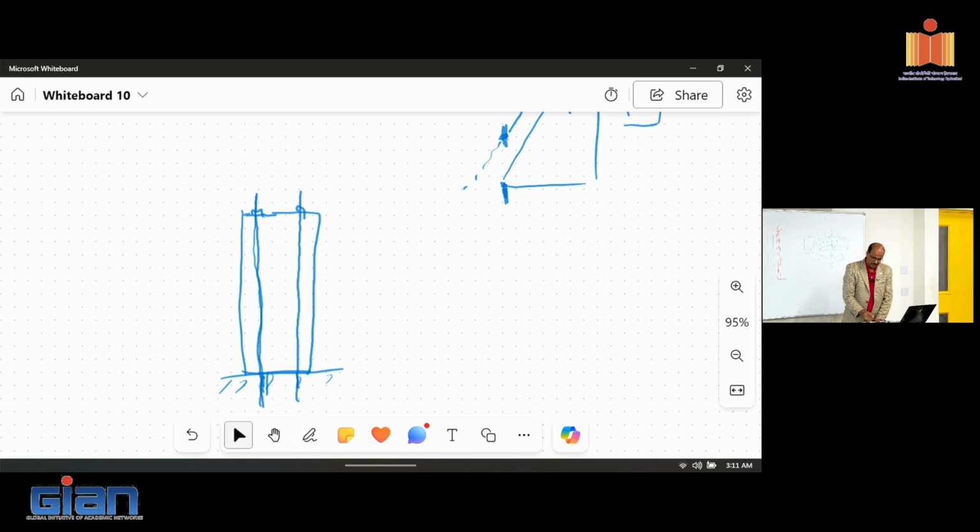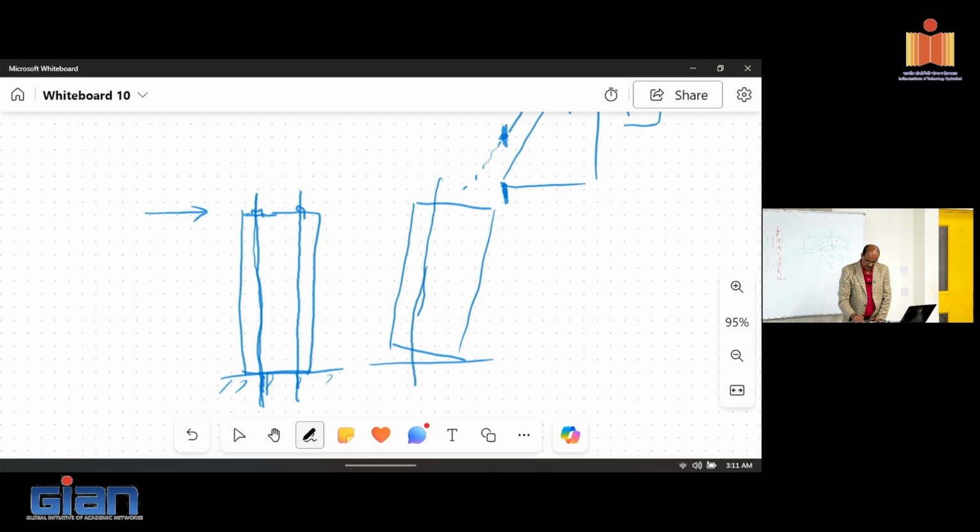So if I push on it, what's going to happen now is this is going to just rock like this. Your strands will be going like this. Here's your second strand. There won't be any crack developing at all because your interface here can open up completely. So there's no reason to develop a crack. If I can keep the strands elastic, and if I remove the load, it's just going to snap back to its original position. The crack should close completely.